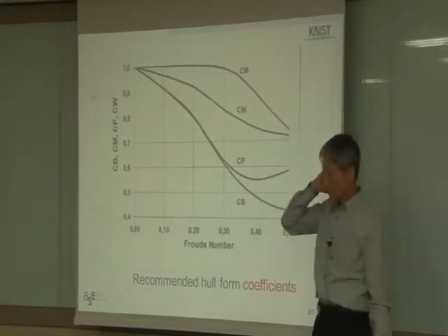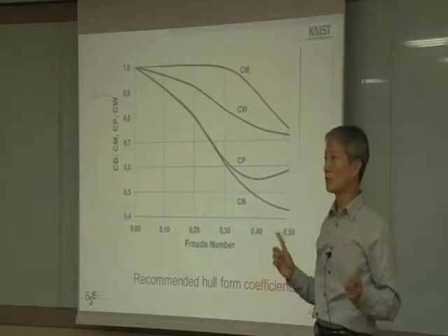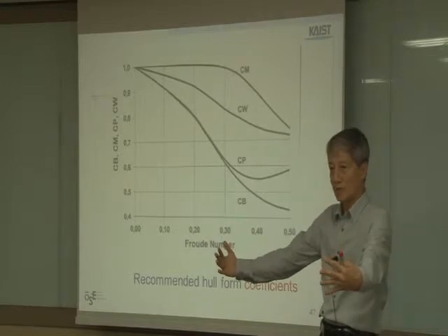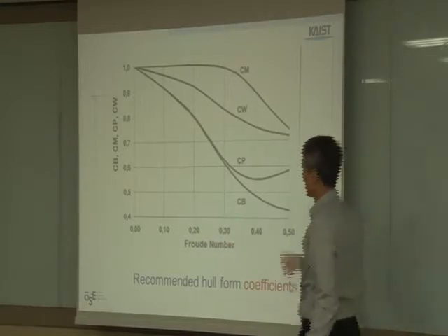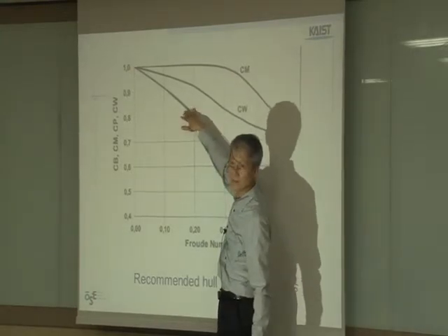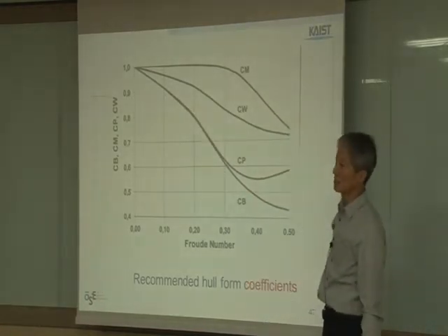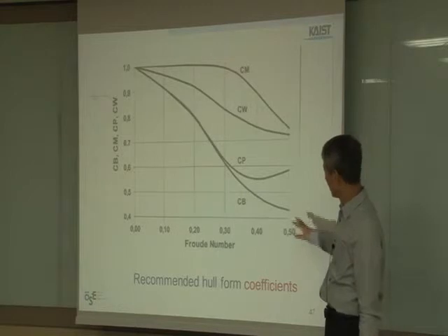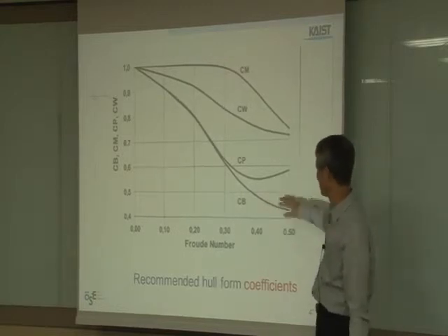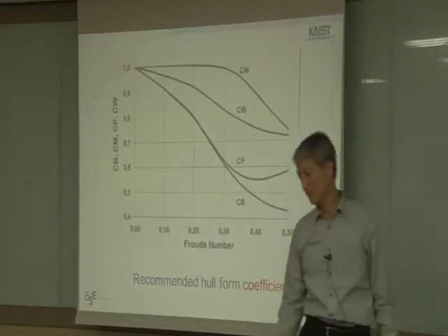So crude oil tankers don't need to have a high speed. They want to bring more and more oil, so they are slow and full. They have a high CB, around 0.8. But ferries, destroyers and warships have a CB around 0.5 or less.